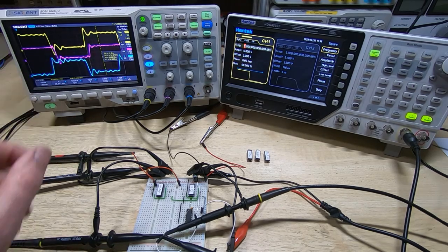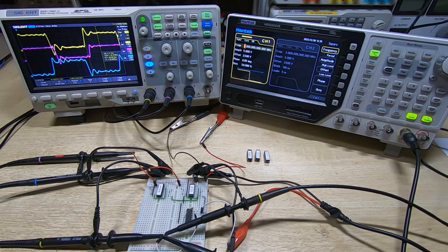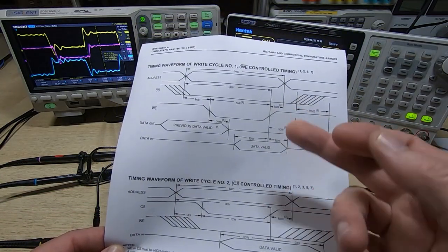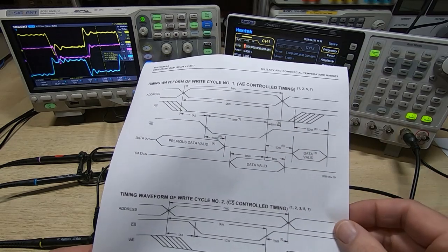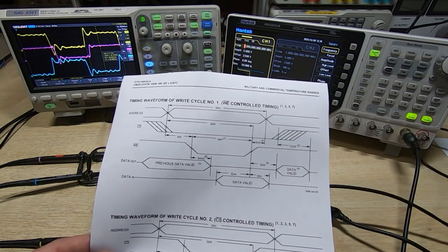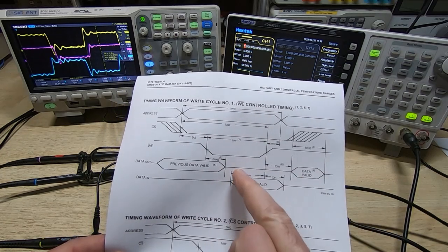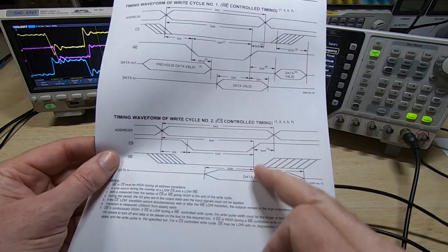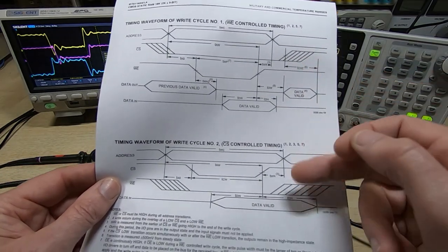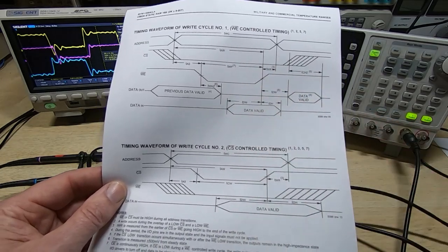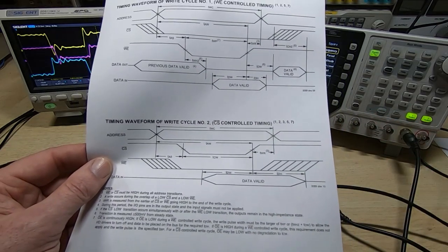But what you're looking for is the relative timing, and of course, because the overall effect is to maybe cause issues when trying to read something like an SRAM, a good place to start is the data sheet for the devices. So if you want to investigate whether you've got an issue with the SRAM, get the data sheet for the SRAM, look at the signals going to it and see if they make sense. Make sure they meet the requirements for the way that the device should be driven. And if the timing is way out, then you may well have found your culprit.